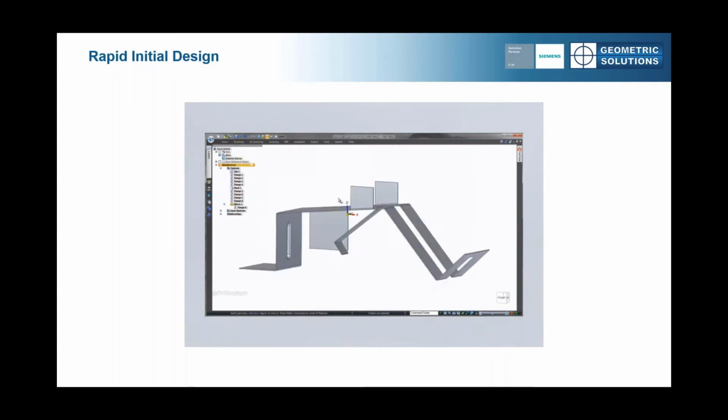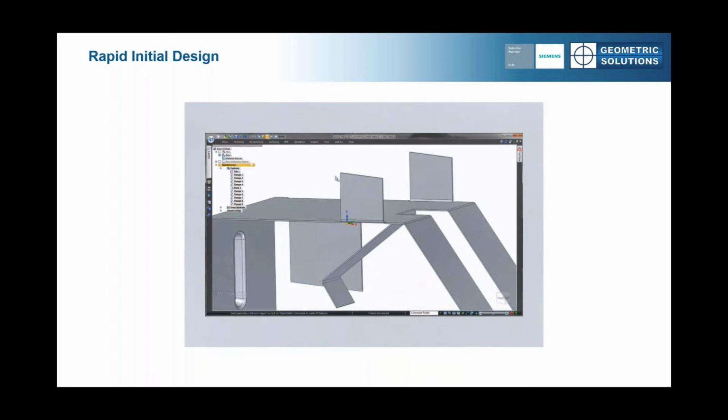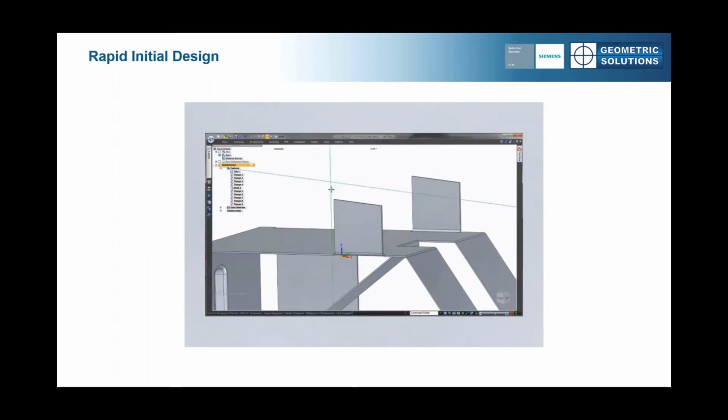Let's get back to working on the clamp for the fuse holder. Remember we mirrored this, and notice along with everything else, this has been added to a feature tree. Yes, it's direct modelling, but there are still features to work with, like in history-based CAD. The best of both worlds with synchronous technology. That means we can edit the feature, breaking the link so that we can work independently on one side. And now we can add the jog that we want on this flange. Same process as the bead here, just a simple sketch line, and then apply the jog.